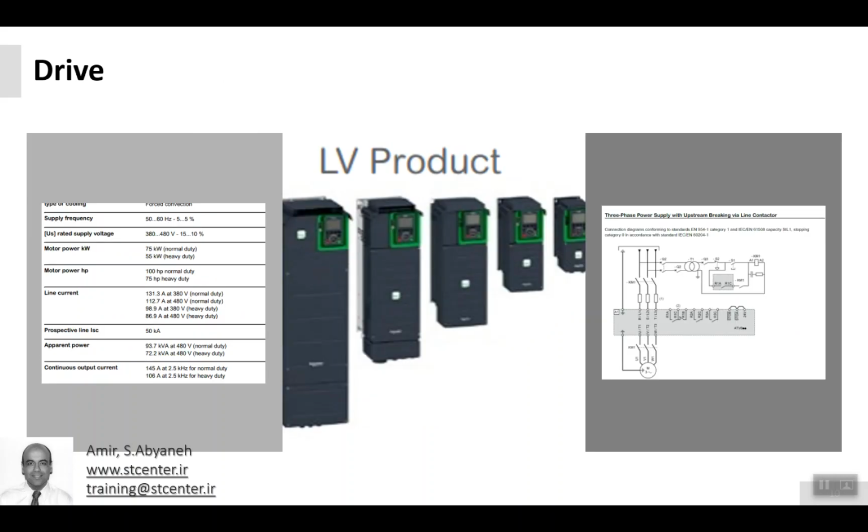In this example I provided for you, you saw that we use the drive to control, power up and supply the motor of the pump. So we should select the drive based on the motor capacity, if it's 1 phase, 3 phase and so on, and what the wattage and horsepower are. We should take care of it, select it, and also take care of the wiring according to the manufacturer's datasheet.